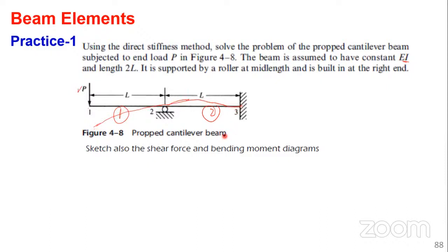Okay, so go ahead. What you first need to get is K. K is standard because here it is the same. Then you get a combined stiffness matrix, so the assembly of the stiffness matrix for the structure. Then you invoke the boundary condition to reduce your matrix and solve for the nodal unknowns.